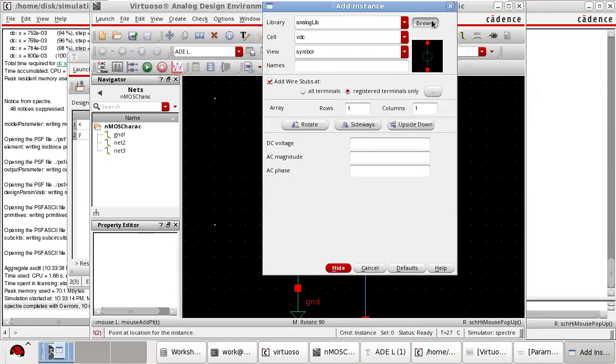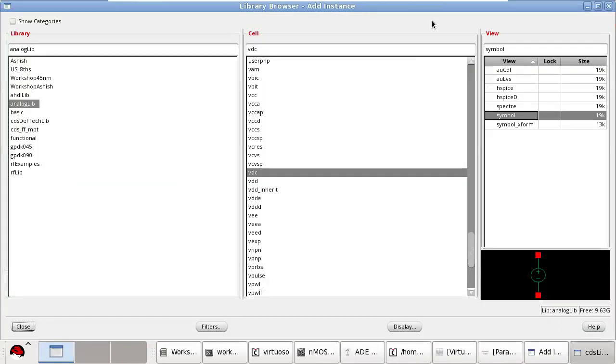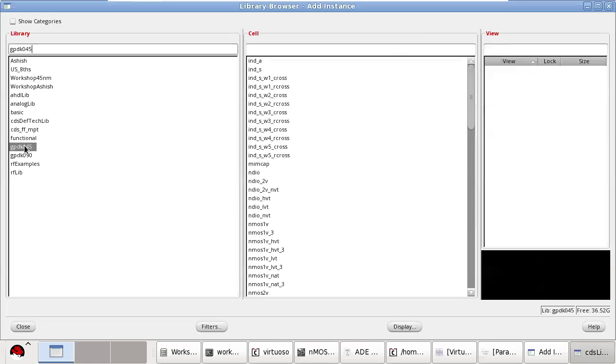In this, what happens is that if you see all these libraries, this is GPDK, generic process design kit. This is for selecting the MOSFET as a capacitor, MOSFET direct, MOSFET as a resistor, low threshold voltage, high threshold voltage MOSFETs, but you do not have the base components in GPDK. GPDK means whatever you can design on the silicon wafer.